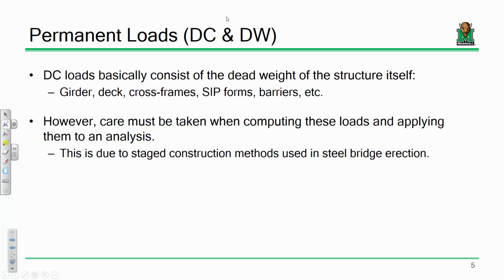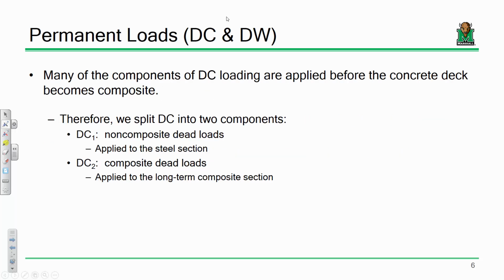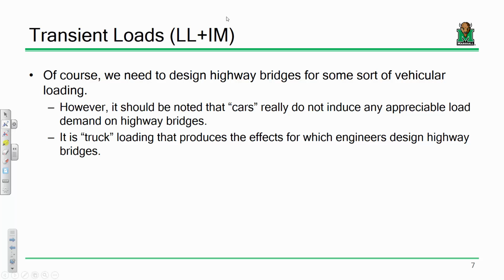We performed what we call in the world of structural engineering a load takedown. You're essentially one by one counting up all the stuff that's put on the bridge and converting it into a structural analysis load model that we as structural engineers can use to say, okay, what are the moments, what are the shears, deflections, et cetera. That's dead loads. Live loads are a little different.